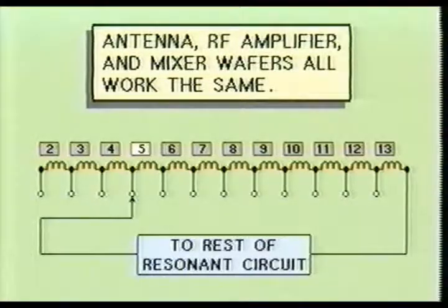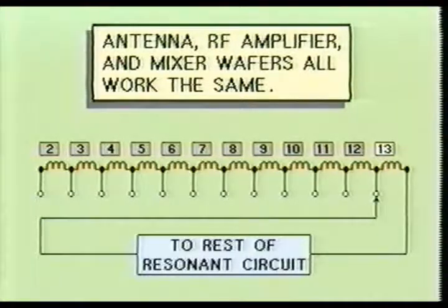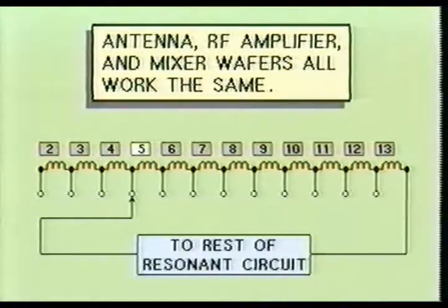The inductance is varied by adding the inductive value of the selected channel when going from TV channel 13 to TV channel 2, or it is subtracted from the value of the selected channel when going upscale from the TV channel 2 to TV channel 13.